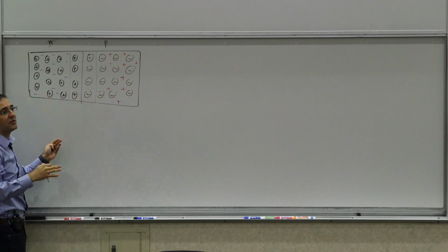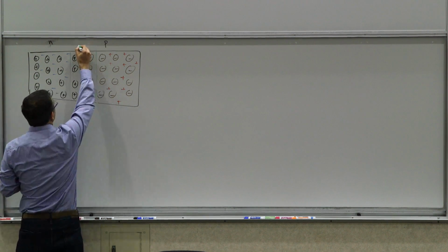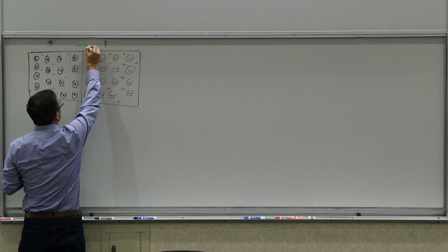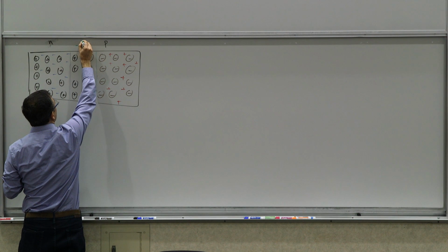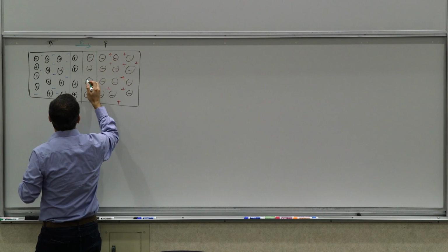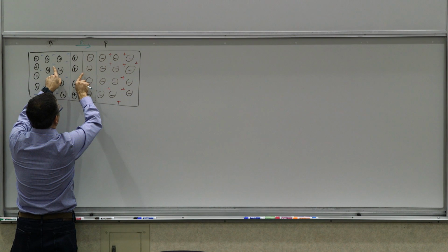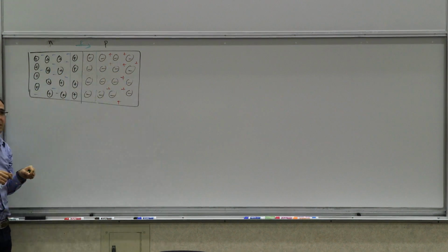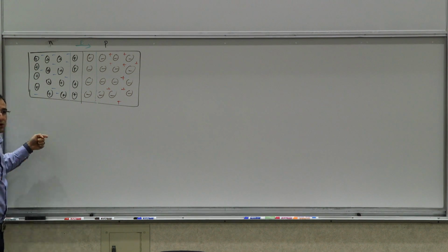Of course, you're constantly generating new electron-hole pairs, and as they are generated, due to the electric field that's generated in this direction, which is basically pointing which way? The electric field, if you put a positive charge here, it's going to go this way, right? So the electric field is pointed this way. So this electric field would force them, so if you have an electron and hole generated, the electron would go this way, where it's majority, and the hole would go this way. And this is basically balancing the net flow, because there's always some hot electrons and hot holes that would just cross the boundary, that would be able to cross this barrier.